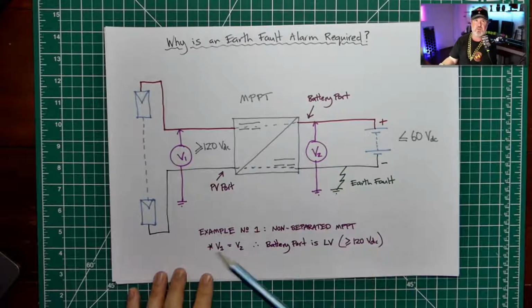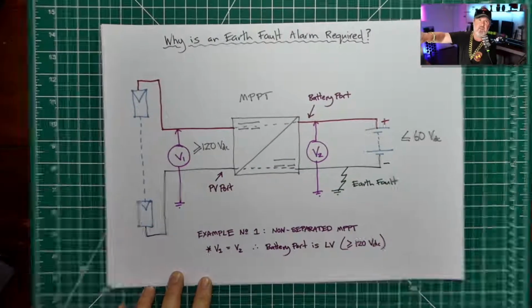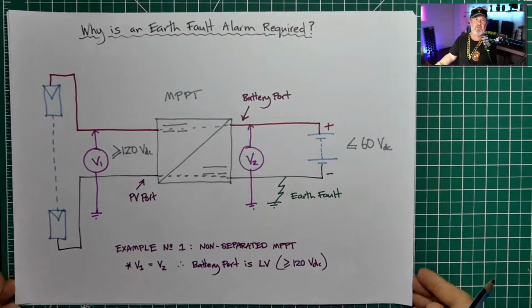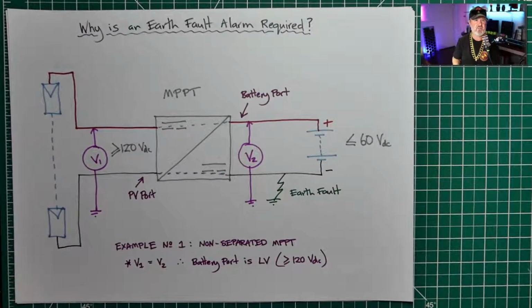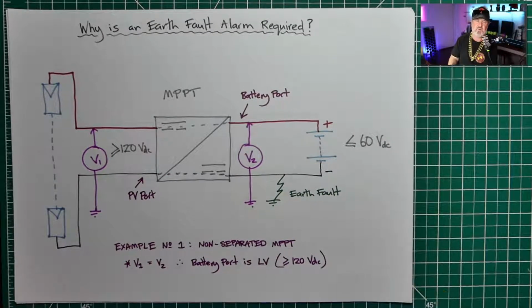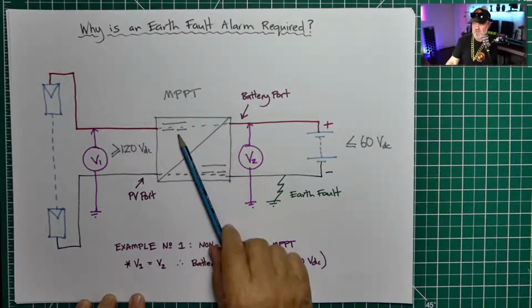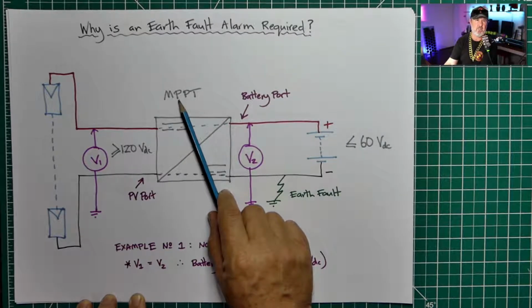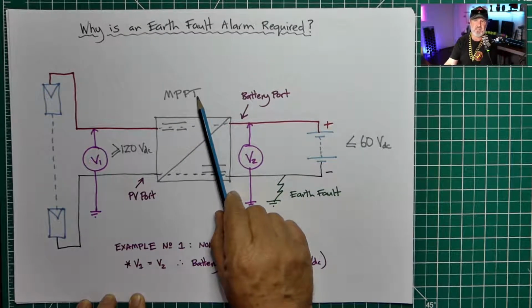Now, a maximum power point tracker, and I should probably zoom in a little bit more, is a DC-DC conversion device and also something that operates generally either a PV array or other devices with variable impedance at the optimum power point. And so, hence the word maximum power point tracker, MPPT.